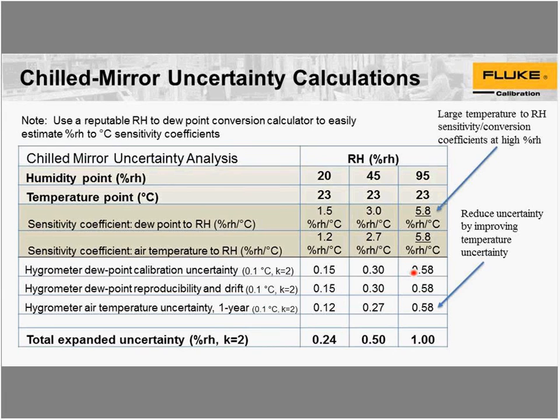That's part of the reason why I went to NIST, because I have a very low uncertainty dew point calibration process. So the other thing is that you could have the chilled mirror calibrated with a really low dew point uncertainty to make it competitive with the two-pressure generator at 95%. I guess that's the final answer to that question.